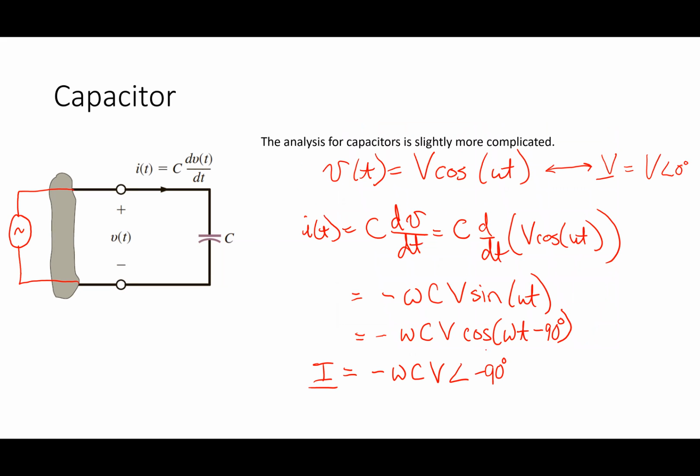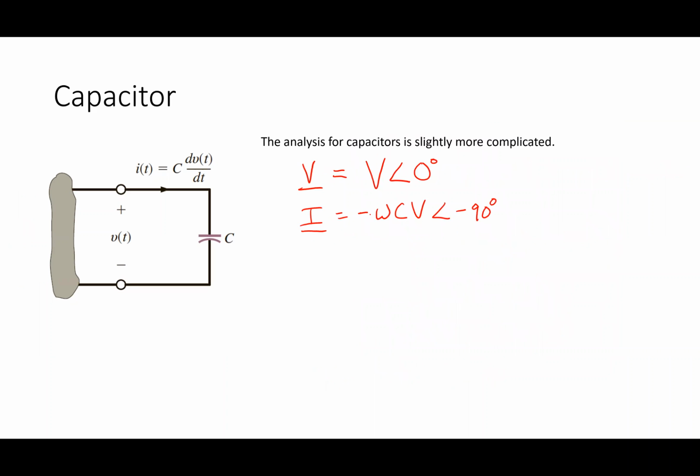So let's just draw the waveforms here for a second. First of all, this angle negative 90 degrees. I got this minus sign out here, and I got an angle of minus 90 degrees. That's weird, because when we use polar notation, I put the magnitude in the front. What kind of number is magnitude always supposed to be? Positive, right? If I have the number -1, that has an angle, doesn't it? It has a magnitude of 1.